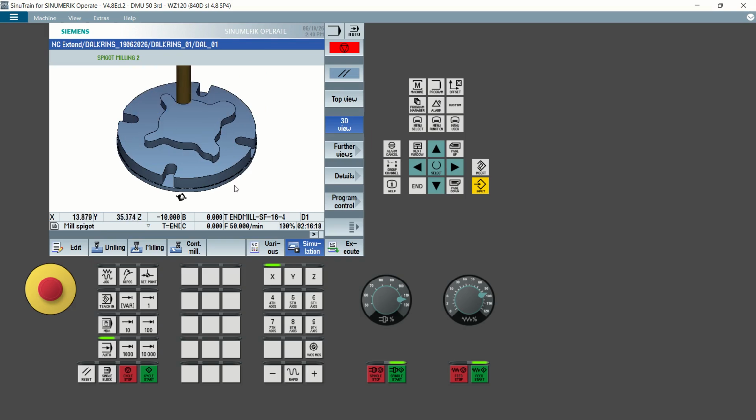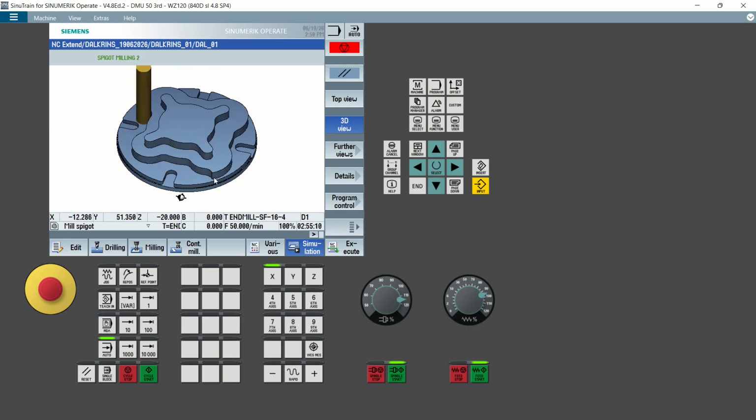Let's finish this one for the purpose of this session to see how you can program without putting in the contours. We just import the DXF file from your design. Or somebody can send you a DXF file, then says, I want you to make this. With the instruction, use the DXF file to import into your software, or the programming software of your machine. From there, you proceed to cut. And this is now the actual machine, Siemens 840D.